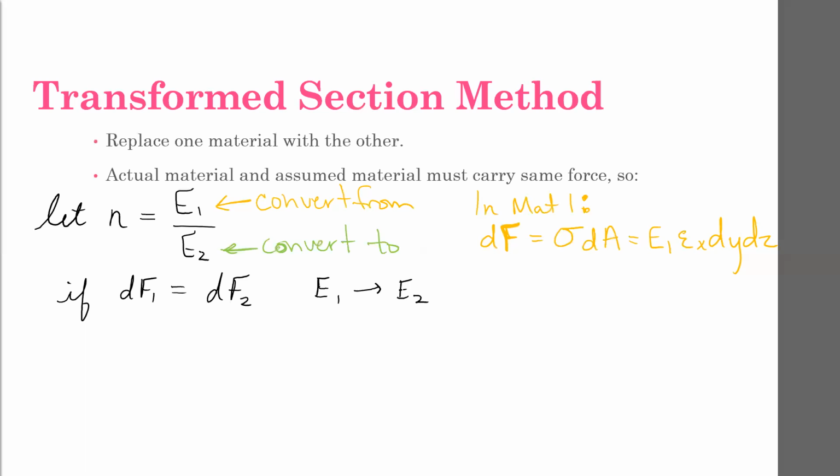Now I'm going to instruct you to only adjust dz. So adjust dz to keep equilibrium. I don't want you to change dy, because if you change dy, now that little area no longer has the same strain value.